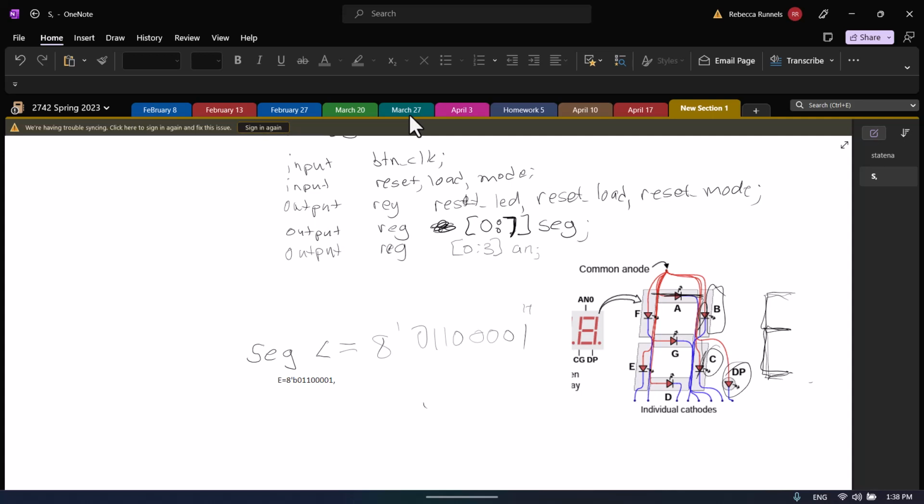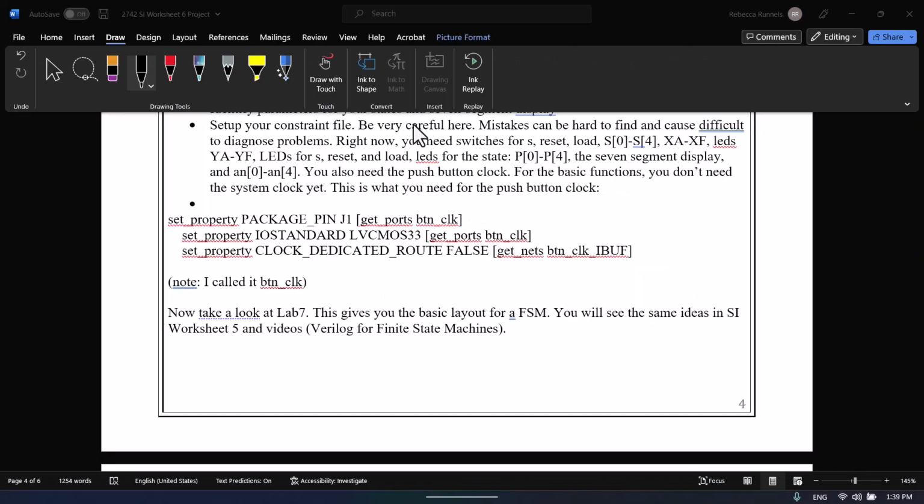And for the basic functioning, you just use the rightmost 7-segment display. So that means anytime you turn it on, that AN is just going to be the 4-bit binary number. Oh, I forgot my B. And you put a 0 in the place of the display that you want it to be. So it'd be 0, 1, 1, 1 to get it to the rightmost display.